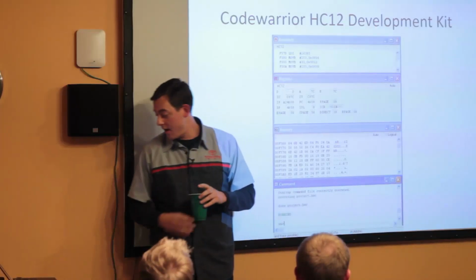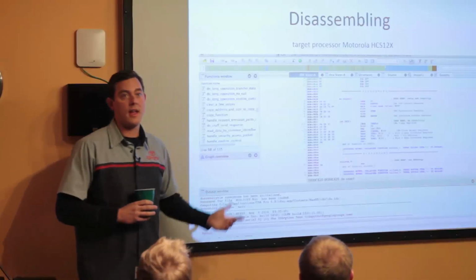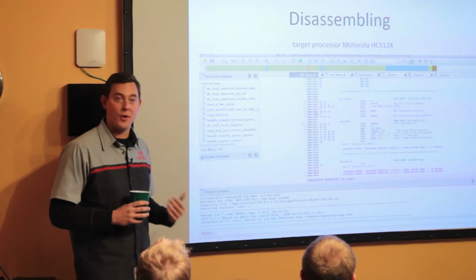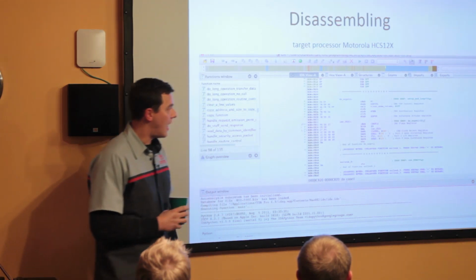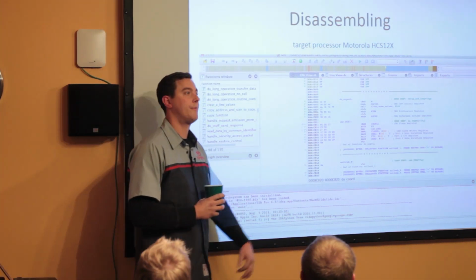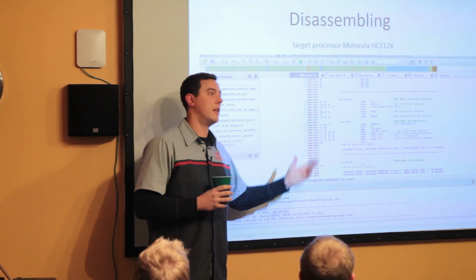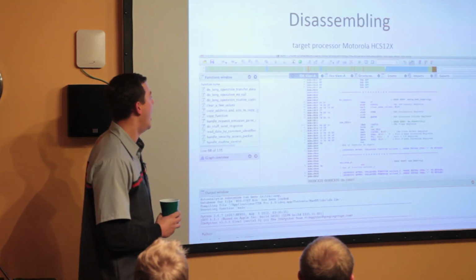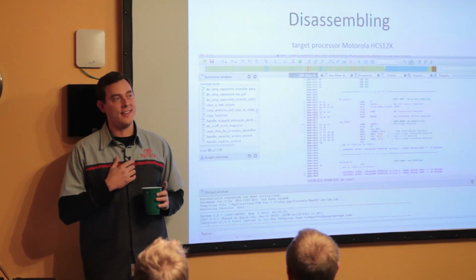We know the firmware and we know the chipset. Luckily, I'd already had a processor module for this Motorola chipset. And again, Charlie and I are software engineers by trade. This is the good part. Like, man, I just want code. All the car stuff is super hard. This is what we wanted to look at: figuring out, based on the architecture, what areas of memory are used as buffers for CAN stuff, how you do interrupts to send and receive messages, and the such. All your annotated function names: do stuff, send response. Oh yeah, do long operation no call. Thorough investigators we are.